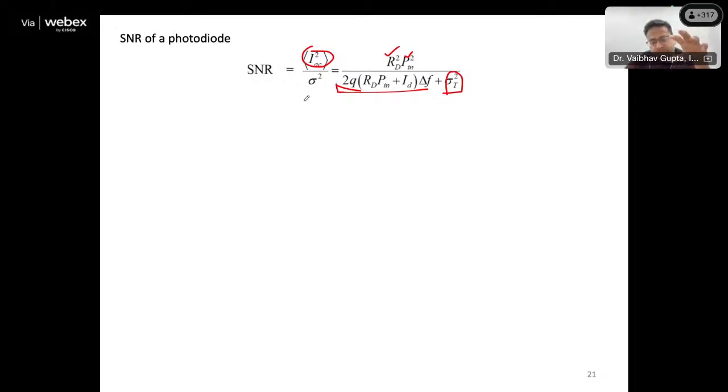And we also know, as we just calculated, that typically thermal noise is higher, which is 0.4 microamp, and shot noise is lower for a lower incident power at the detector, which is 0.02 or something. Now typically, there are two regimes in which a detector works. One is the shot noise limited regime. Previously we also talked about that in the quantum system, we have to work with the shot noise limited cases because the source itself is giving a noise in the arrival of the photons.